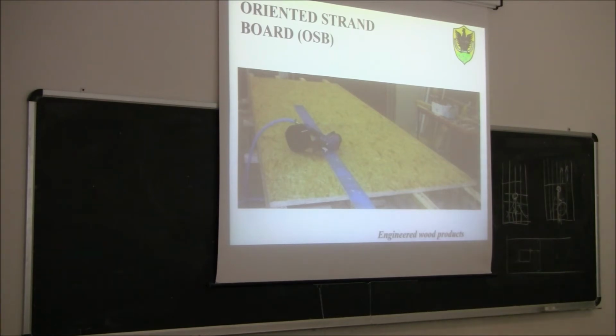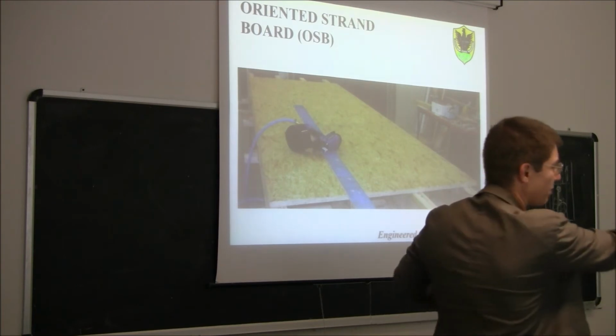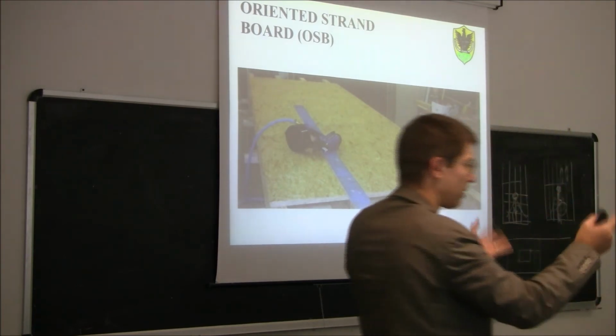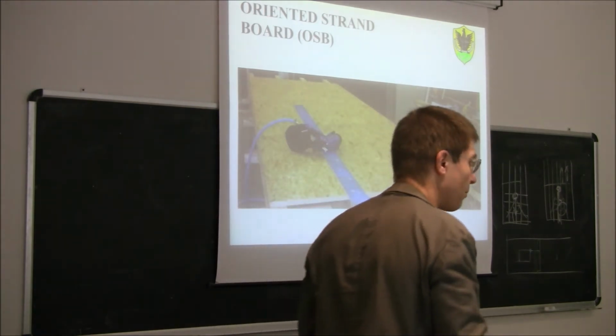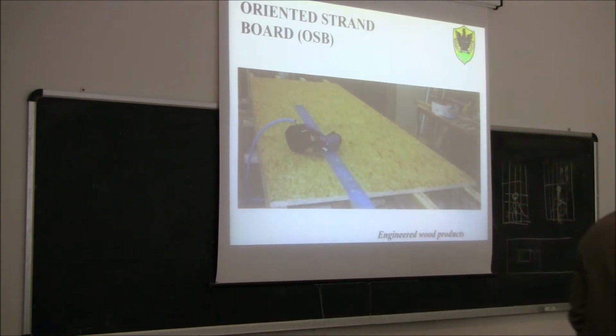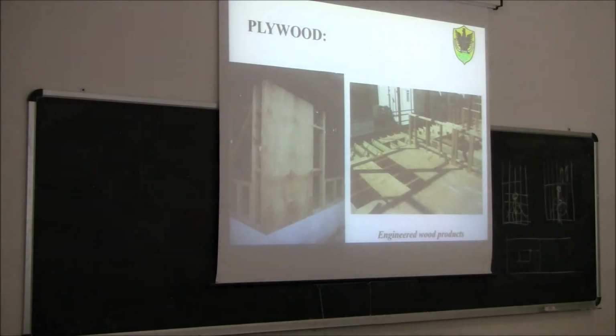Also here, if you go outside, you will see that this is being used for one of those buildings on the right hand side, all around, so you can see this oriented strand board. Oriented strand board has better properties compared to particle boards, and I would say worse compared to plywood. It's used quite often in our country for light frame construction. So if you do these walls like this, as I will tell you before, very often we use in Italy oriented strand board instead of plywood.